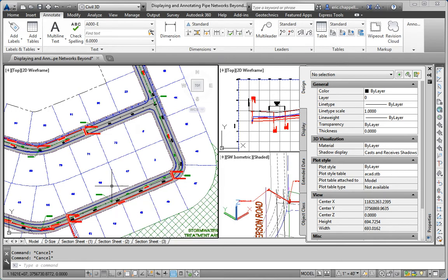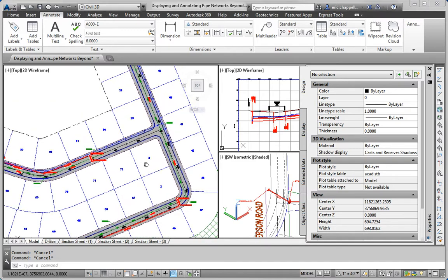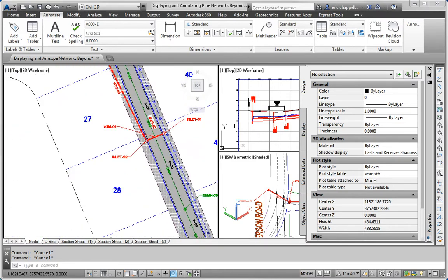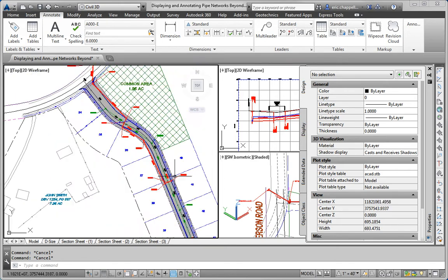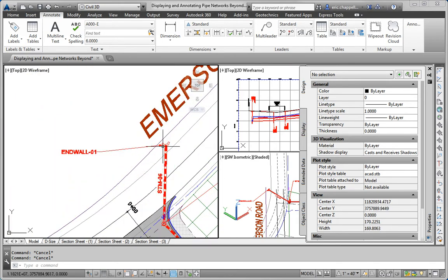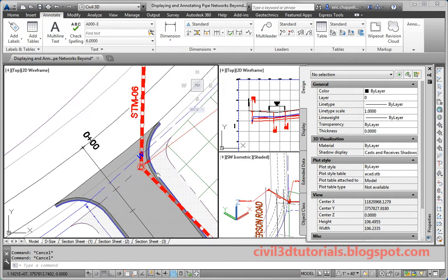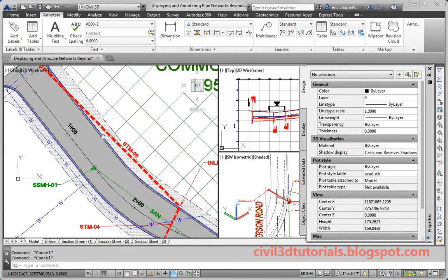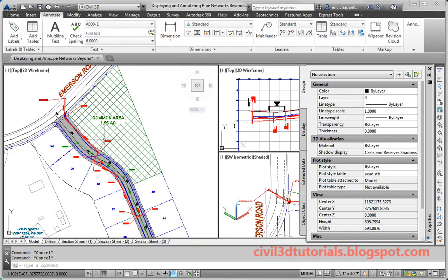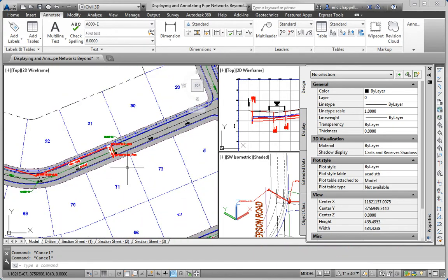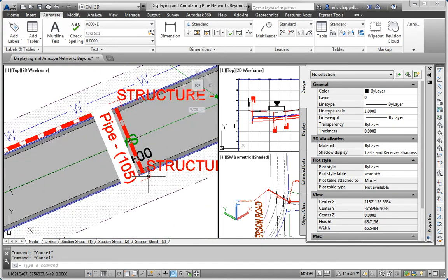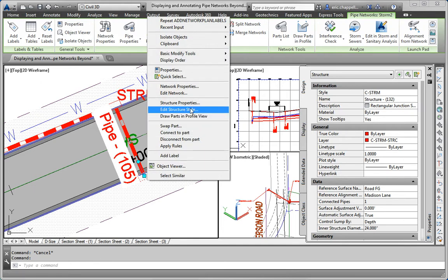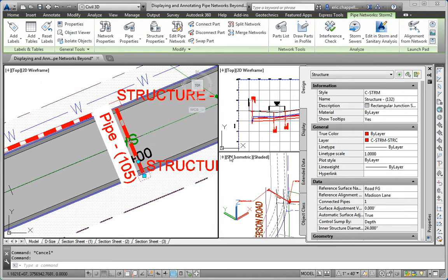It says to rename the storm pipes and structures to continue the naming and numbering system that you've used so far. So if we look at the names we have now, we ended at N-Wall 1, Storm 6, Manhole 2, and Inlet 4. Alright, so our first inlet is going to be Inlet 5. So I'll go to the Properties command, which I already have open, and I'm going to change that name to Inlet-5.